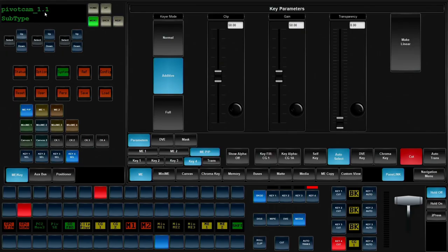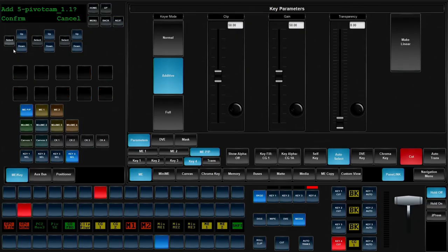We're going to find our pivot camera in the subtype. Click next. Enter our IP address, so 10.0.1.248. And now we need to do our port, which we did 2567. You'll notice you have no other options. You click next, you're back. Now we hit select, confirm that device.